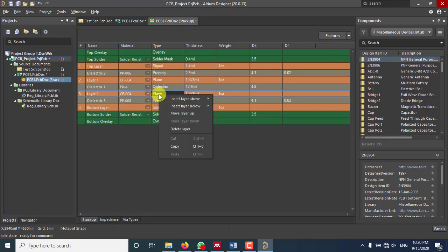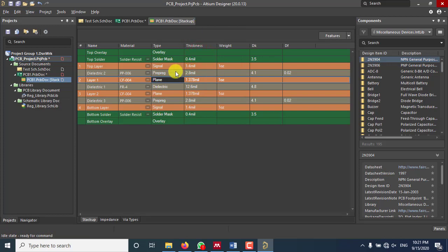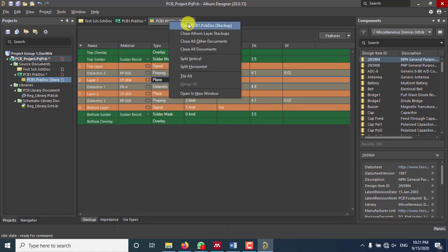And as I said, on the signal layer you can put those tracks, but on the power layer, on the planes, you cannot put lines. You can just divide them into different sections. So let me just save this, for instance. And please remember that this now becomes a 4-layer PCB. Previously it was a 2-layer when there were only the top and the bottom layer.